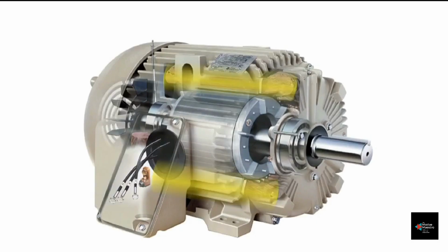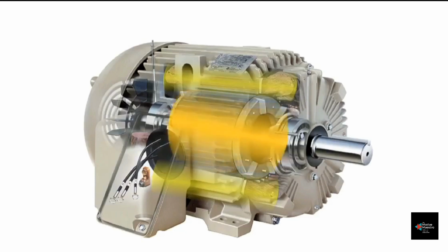Correspondingly, the relative speed between rotor and the magnetic field increases, which causes more EMF to get generated on the rotor conductor, resulting in more rotor current and more force. Thus the motor again exerts more force to keep the relative speed to a minimum by taking more electric power.